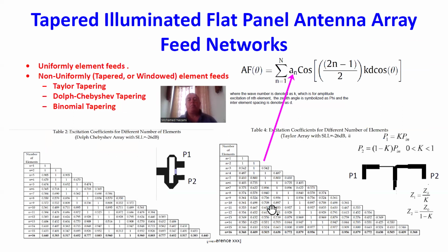If you have an antenna, it turns out antennas are like, for those of you in signal processing, if you take a pulse and you take the FFT of that pulse, depending on the post processing on that pulse, you can get a different way of representing the energy from that pulse. Now, if you FFT a pulse without any windowing, which we call rectangular windowing, you get exactly the sine x over x.